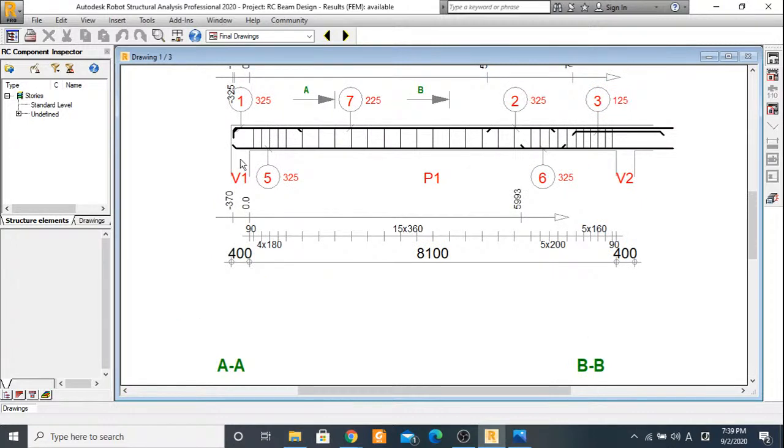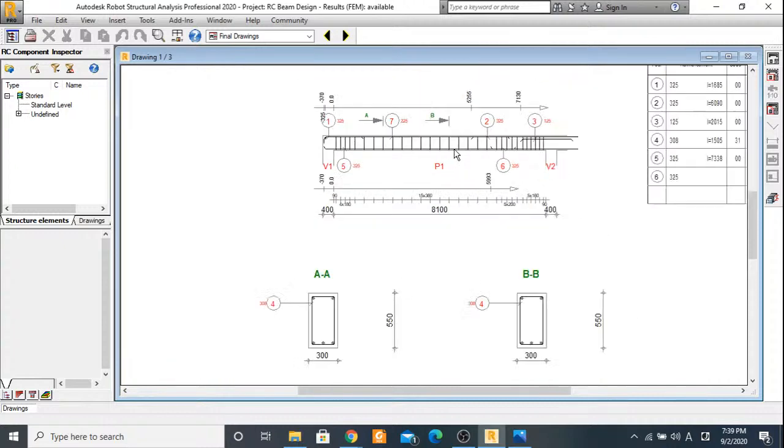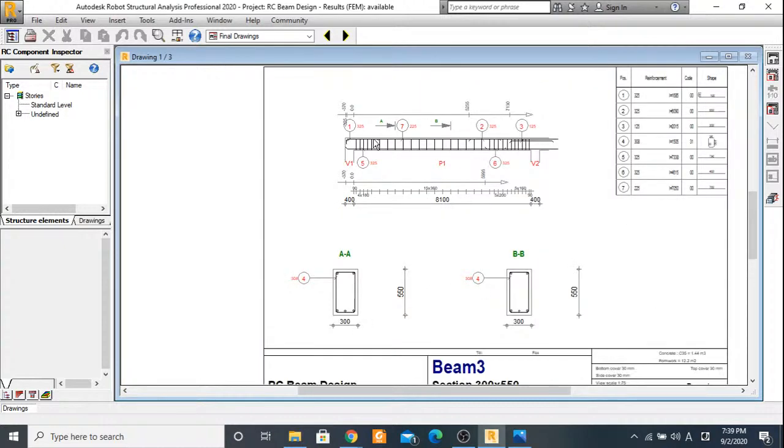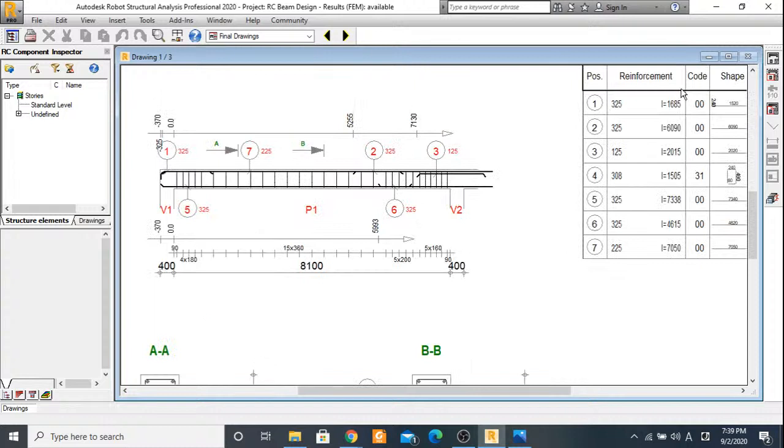So it is certainly those two that they call, no, not the two. If I cut here, there should be 2 bars, I'm sure. All right, so here we have 3 bars of 25, and then here we have 3 bars of 25 down this way, and then we have our shear links this way. All right, we have our shear links this way, 4 of them spaced at 180, and it goes on and on. So you'll notice that the spacing between the shear links towards the support is small, right?